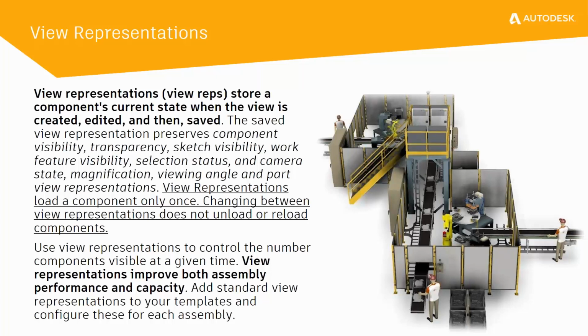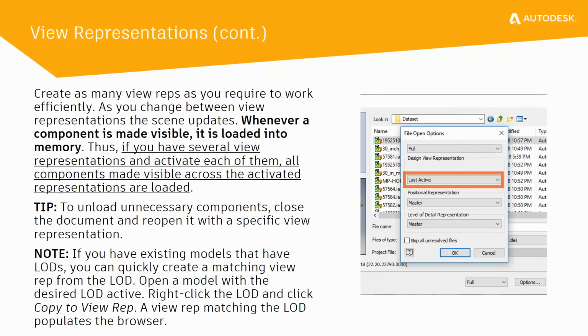When you load a view rep into memory, it loads all of the components that are required based on the visibility of the component. But the interesting thing is that when we switch between several view reps, what in essence happens is that any component that has been loaded into memory stays loaded into memory. So if you switch between numerous view reps, what you'll find is potentially over time more and more components are being loaded in memory. The only way of unloading those components from memory is to close the document and then reopen it to the view rep that you want to, which you've got the option to be able to do as well.